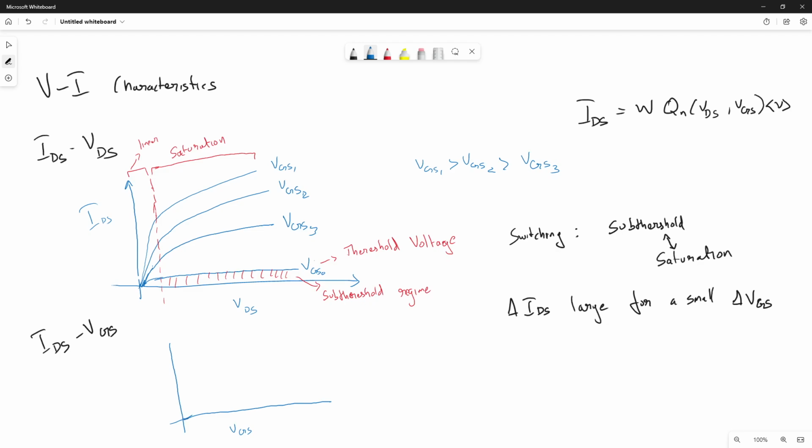Yes, so that is the sub-threshold region. Now this VGS, which I called the threshold voltage, so there will be a VT. Okay, and after that, what will happen? After that, the rate of increase will not shoot up vertically, but it will increase. Yes, it will increase much more rapidly. Okay, so it will increase much faster. Typically, you will see that there is an exponential relation past the threshold region. Like in your conventional MOSFET formula, you will see that a similar relation exists in our case also.